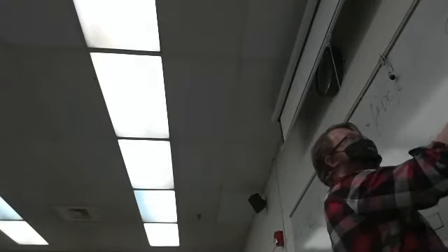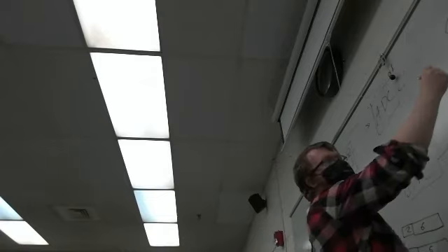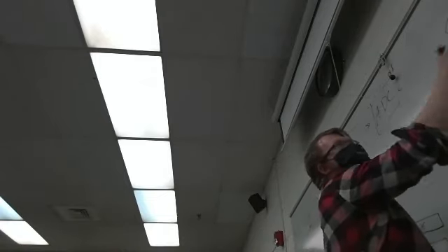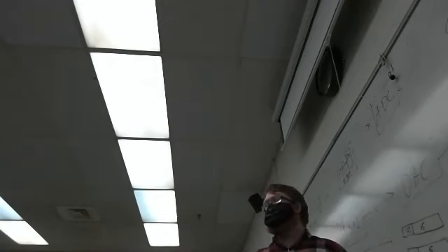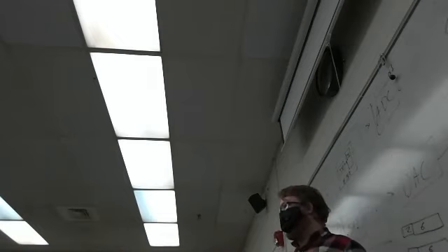They're not hard. One of the simplest filters is a rolling average filter, where you just take some section of it, you take the mean of that, and that's your new point. And then I move that over and take the average, and that's my new point. And I move that over and take that. That's what I was asking, like, how do you implement it in VHDL? Yeah, so that is one of them. That's a moving average filter. It functions like a low pass filter really well.